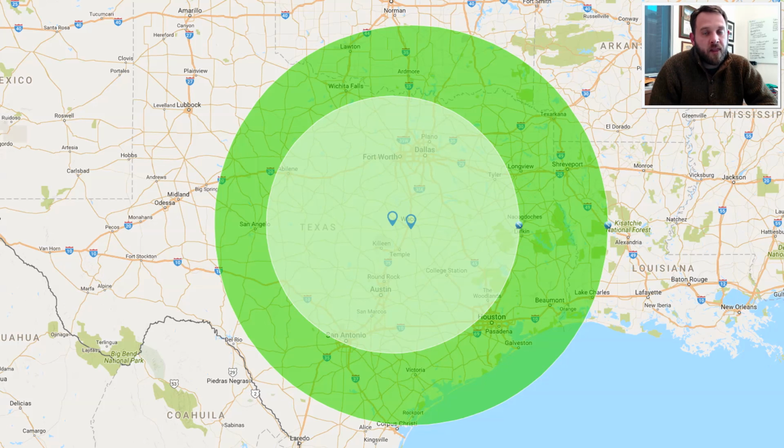That's in theory. The radio actually ceased to function at about 60,000 feet on the ascent. Part of it had to do with some configuration issues that wore the battery out. The battery expired. But from 55 or so thousand feet at this location, our radio horizon was more like this white circle. This was the effective range, what we got out of it.